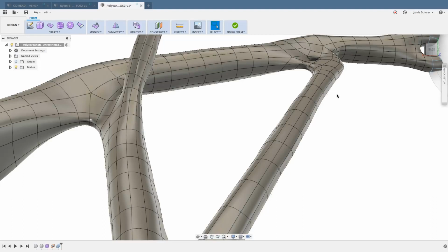It's one of the beauties of working in the Sculpt workspace that it always maintains G2 continuity, which means that the transitions between the faces and edges are always perfectly smooth. No seams, they stay perfectly continuous. But just the same, as you have more and more of those edges in really close proximity to each other, you're forcing it to make big curvature changes in a small space, which is where you start to see some of that chattering or that unsmooth edge that we had before.